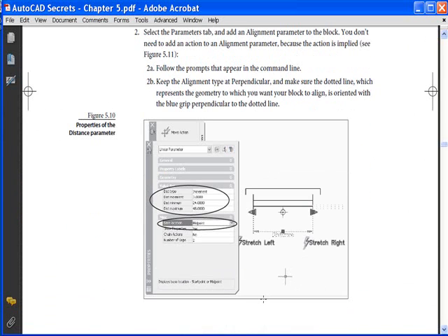Let's go back to the handout. Now if you go ahead and take a look at this handout, there's a value set property, and that value set property is not for the action, it's for the linear parameter. And on the value set you can have a type of distance, incremental, a minimum size for something, a maximum size for something, and then have the increment. So this is a window.